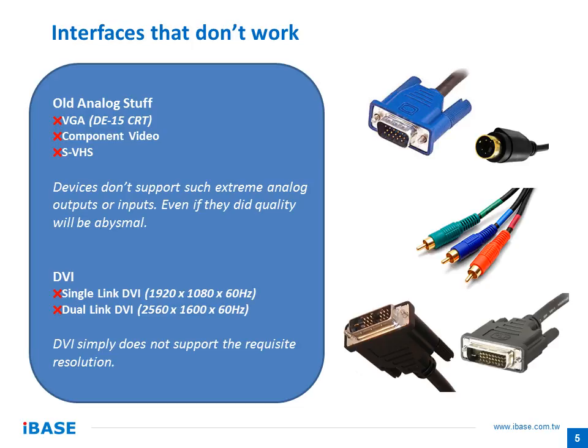These are the things that don't work. These interfaces, if you have any of these interfaces in mind, or if your infrastructure contains screens and players and whatnot that are connected by any one of these things, you can forget about it. You need something else. The old analog connections, like the VGA connector, the S-VHS connector, component video, either don't support those resolutions, or even if they did, given that analog really doesn't have a fixed resolution, the quality would be abysmal and you wouldn't want it.